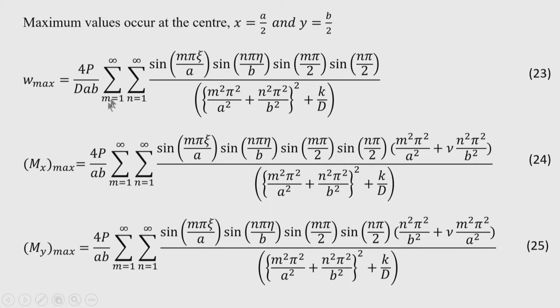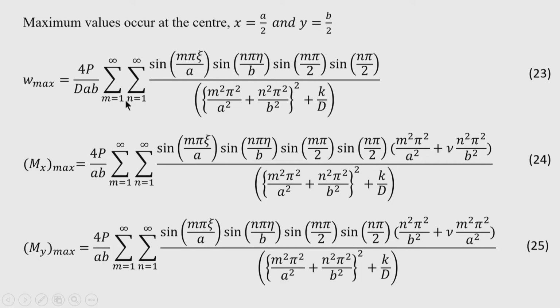expression for maximum bending moment in y direction. So, these are the expressions that are very important, especially for design of deck slab in the bridge, because we are dealing with several concentrated loads. UDL is there, you can take it as a superimposed dead load or self weight, but the concentrated load, that is the vehicle imposed load, can be treated by this formulation